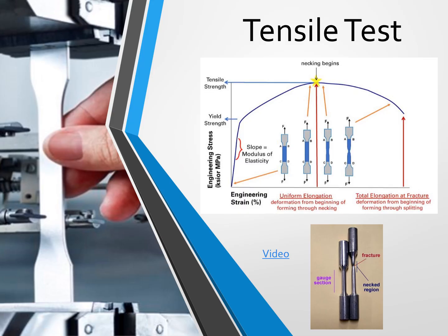So now that we know what stress and strain are, they help us to describe the material behavior independent of sample size. So let's look more closely at some failure. Tensile failure is, again, when we pull on something, and it typically stretches and then causes the cross-sectional area to become smaller and smaller until it eventually breaks.